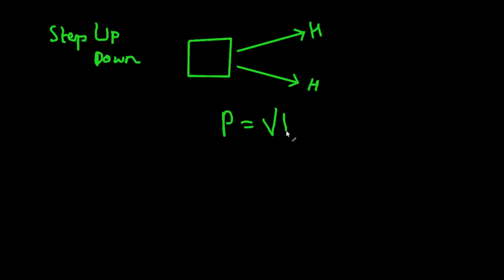Now, one thing is for sure, when we're transmitting from the generator sector to the houses, we have a constant power in watt. The unit is watt, so a certain watt amount of power. So we need to keep this constant. And with that, we can say that there's an inverse relation between V and I. If you increase V, I decreases. If you decrease V, I increases, because that product is a constant.